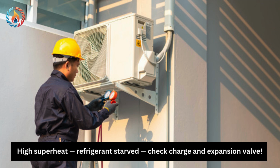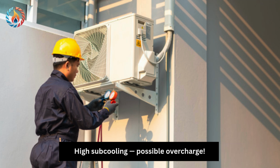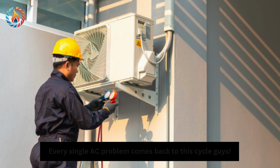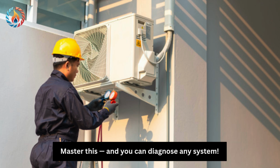High superheat, refrigerant starved, check charge and expansion valve. Low subcooling, check refrigerant charge, check condenser. High subcooling, possible overcharge. Every single AC problem comes back to this cycle, guys. Master this and you can diagnose any system.